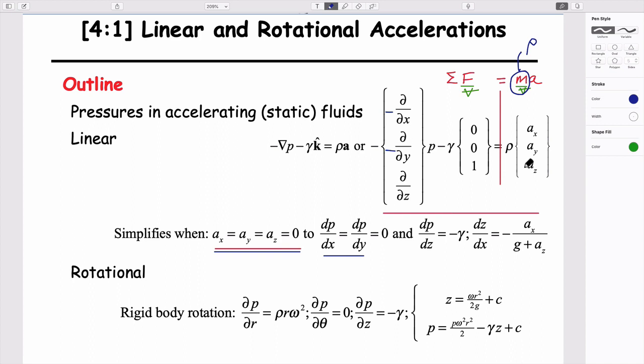The second one, which we've used much more usefully, is that if you go up and down in a fluid, then at least in a fluid where density is constant, the pressure is equal to something like this. And we've used this expression. This expression comes directly out of integrating this when density is constant, but we've thrown away the acceleration terms.